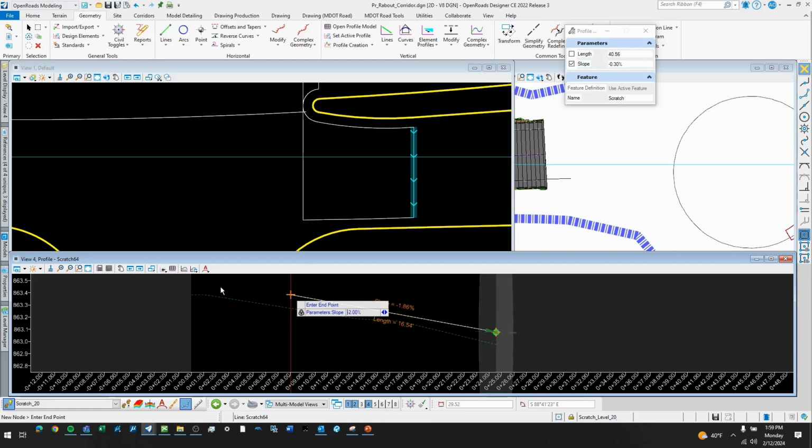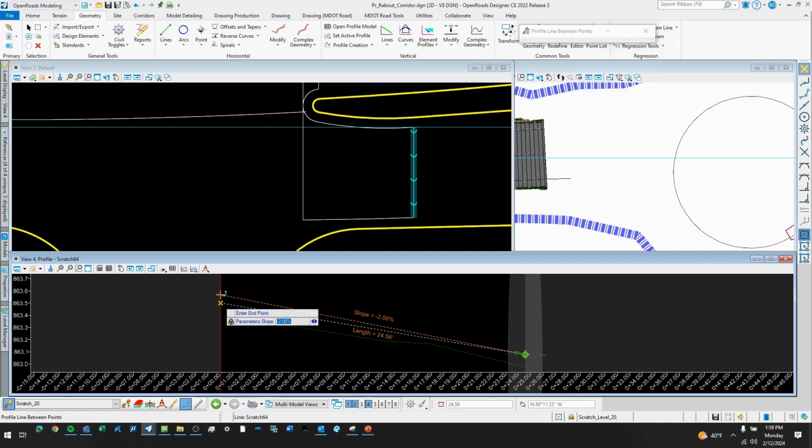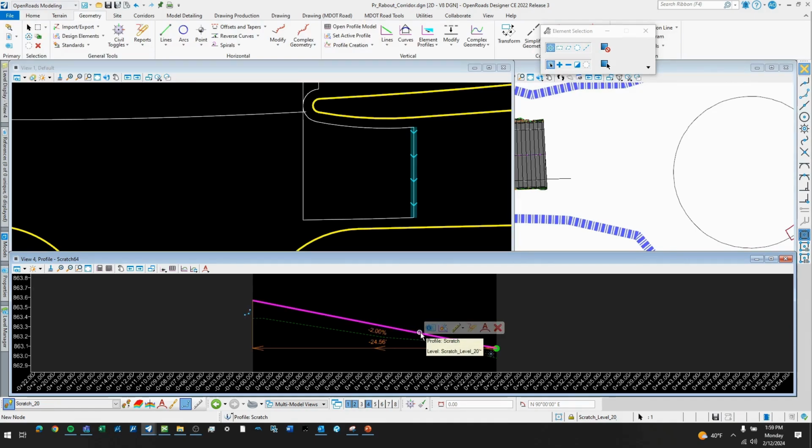If you change one element, it'll all change with it, ideally while holding some of these rules true, like the 2% slope and whatever this point is, and that'll change all of your other things. That way, if you change that slope from 0.3 to like 0.4 on your alignment right here, everything else gets tweaked along with it.